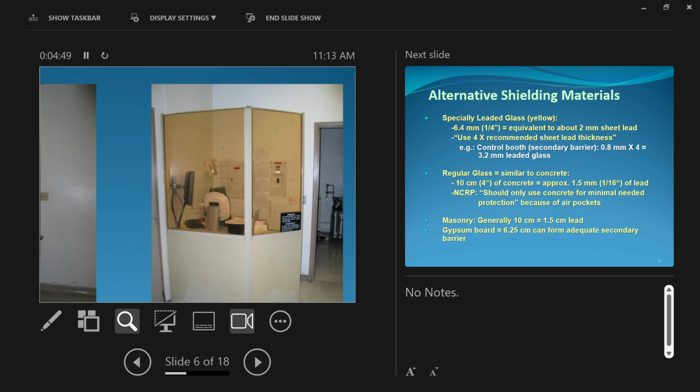Now you'll probably see a lot of rooms where the wall actually goes to the ceiling, right? But if you were to check behind the drywall, the lead would probably stop at 7 feet. There'd be no good reason to continue the lead beyond 7 feet because lead's expensive to work with, and it's a difficult material to fix in place, so you don't need to put it up higher than 7 feet. You could, though, if you wanted to spend the extra money, have your facility be a little extra protected. But yeah, only 7 feet high, okay?